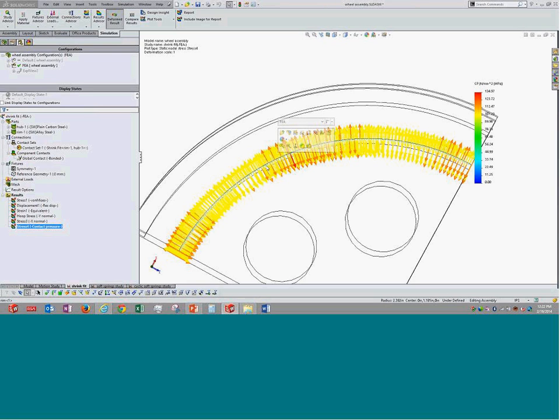Can you please repeat on the global bonded contact number, or why it is used? The contact has no significance in the analysis. You can simply delete it and you will get the same result. It is present just because whenever you create a new study, it is one of the default options. They don't want to edit it.